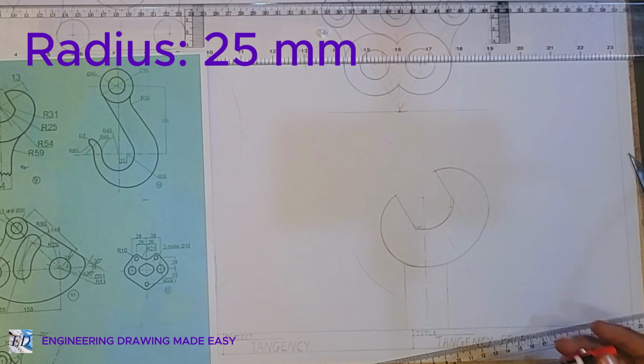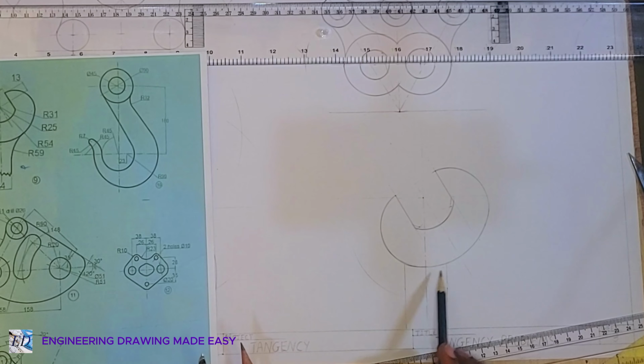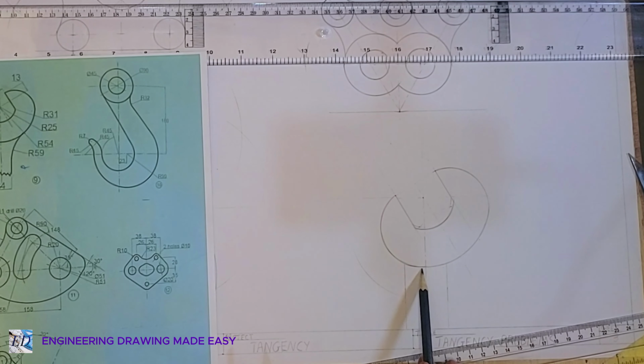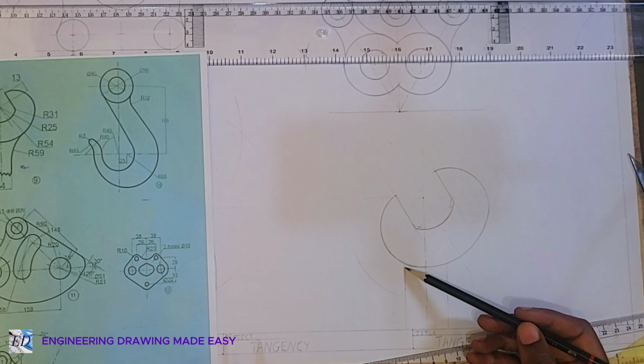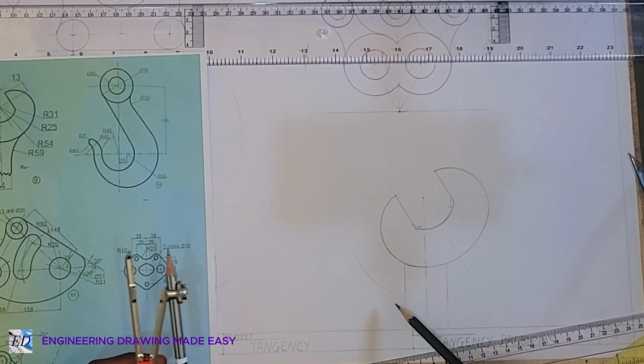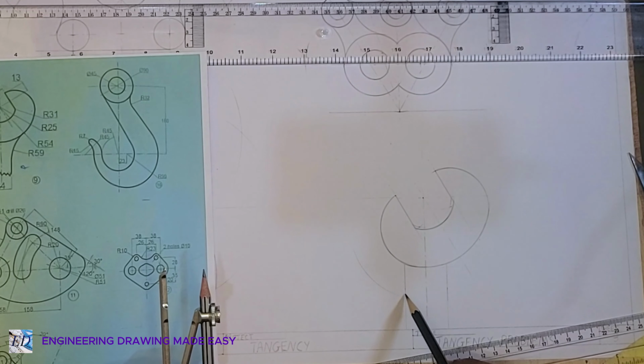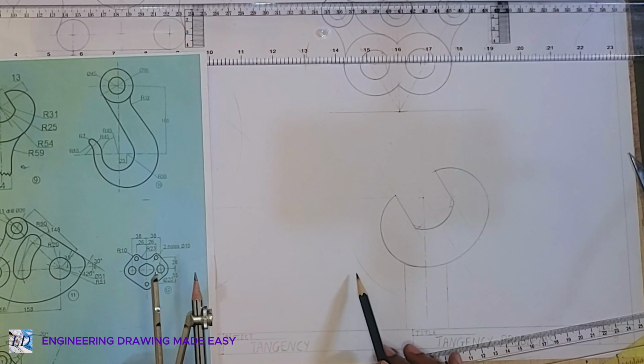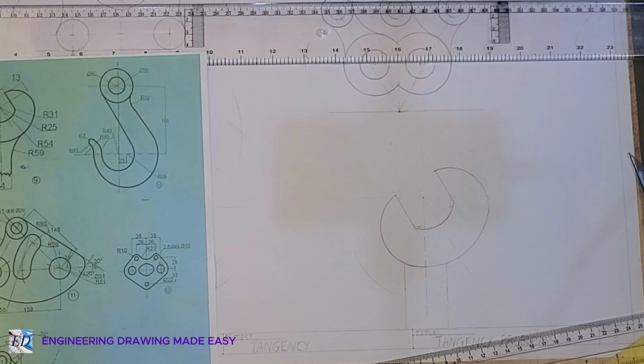Ideally, what you're supposed to do is that you see this part of the work is an arc, right? So you'd have to draw another horizontal line here that is perpendicular, and then from there get exactly the distance from that point to the 25 points, and then use that to try and find the distance or the center, like the usual process that we've been doing, trying to locate the point where the circle touches the line at exactly 1 point, and then use that to find the center of the arc.